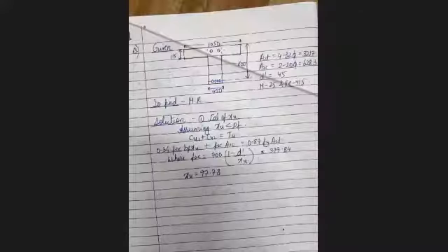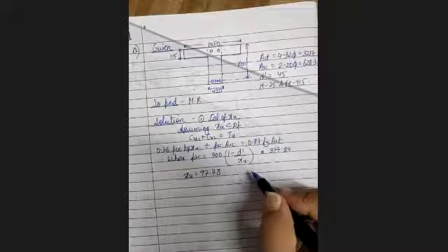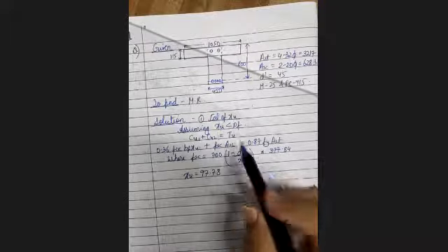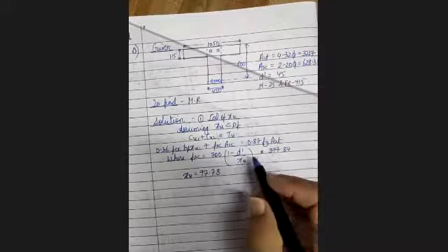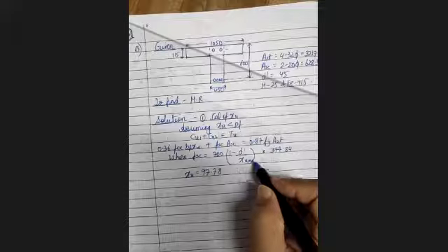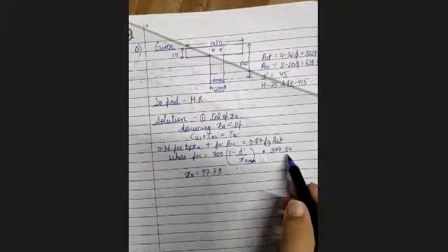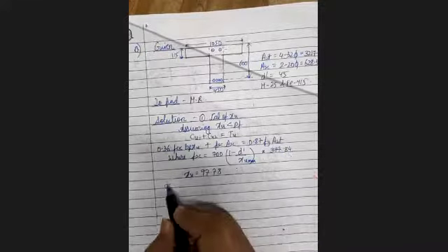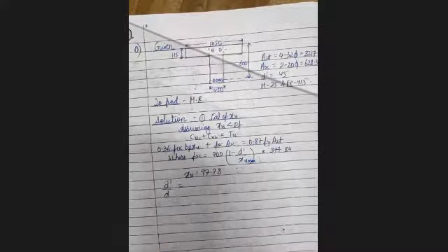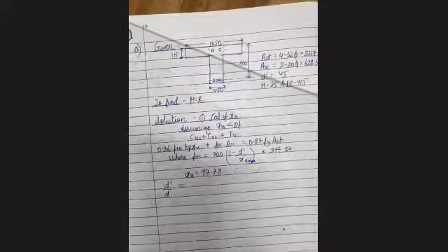So in the last rectangular doubly reinforced sections, what we have done? First we took the value of FSC and then we calculated XU, correct? So we checked FSC from XU max also and from the table also. Whichever was the least value, we took that value, correct? So here also you can check the same thing. FSC from XU max you can find out, and FSC you can find out by D dash by D ratio also. So whichever is the least value, you can consider that, and then you can find out the value of XU.